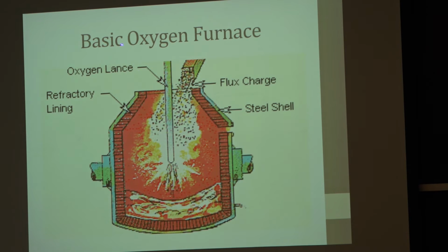This is a water-cooled copper trough. This is the same kind of size. Actually, it's about 5 or 6 stories tall. You only put a little bit of steel in the bottom because when you blow this oxygen in, it's coming out and expanding and it's supersonic, you form a froth.